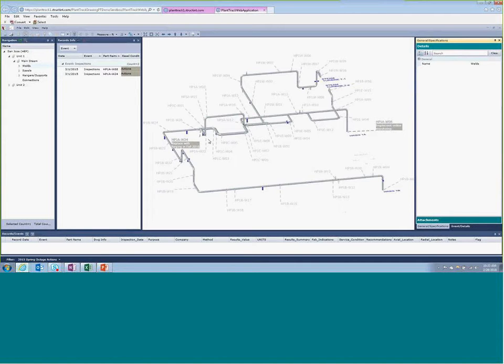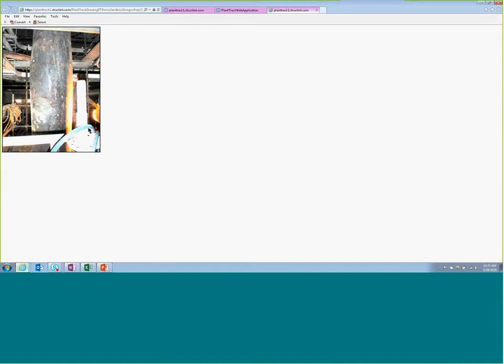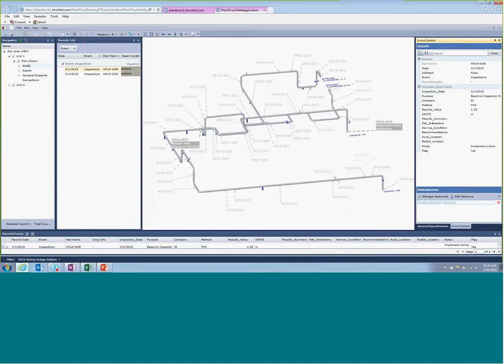Now about this other weld and the spool, that's different. We didn't see any obvious damage. Obviously the hardness was low and the thicknesses were globally low, but nothing popped up that really said, hey, there's something going on here. But we know that there's going to be a reduction in life from a creep standpoint, with the generally reduced wall and the low hardness. So one thing we want to avoid is a nightmare. What we want to do now is place this particular spool on a monitoring protocol.